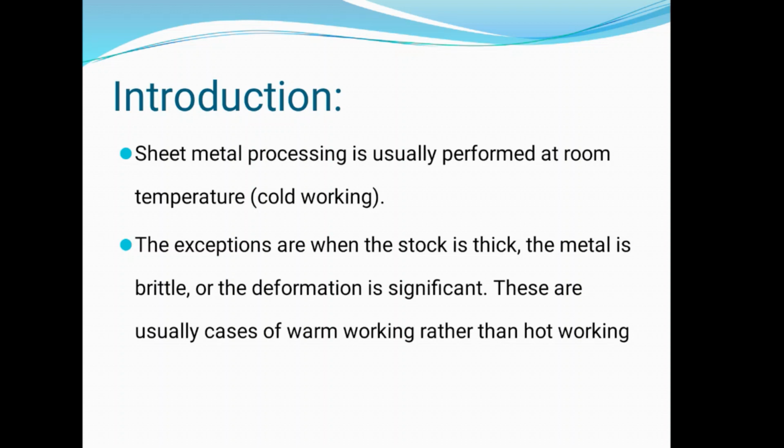Why? Because they do not melt easily. So those are used in the hot working process, that means above room temperature, above the critical temperature or recrystallization temperature. What is the cold working process? The working occurs below the recrystallization temperature. But in the hot working process, the working occurs after the recrystallization temperature.